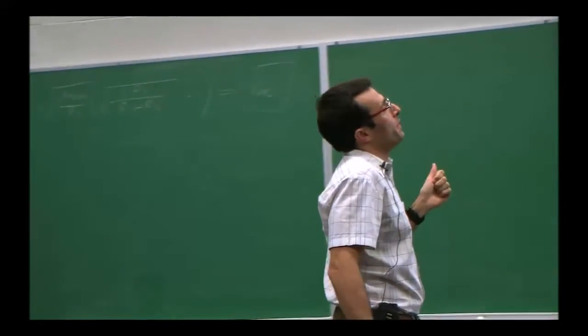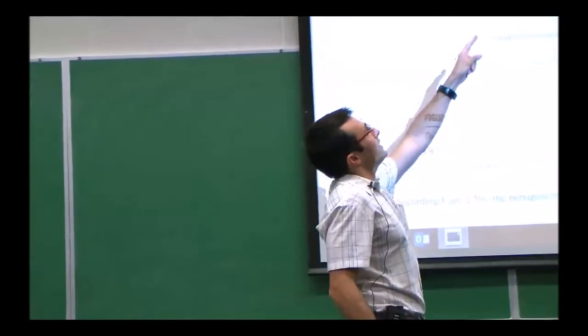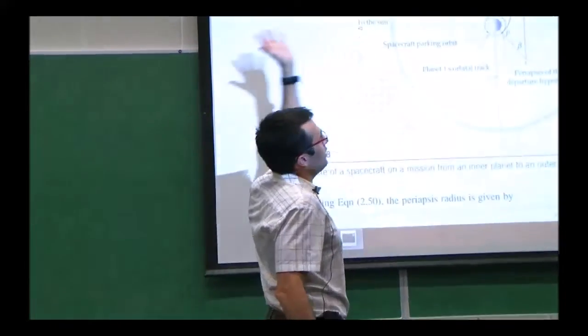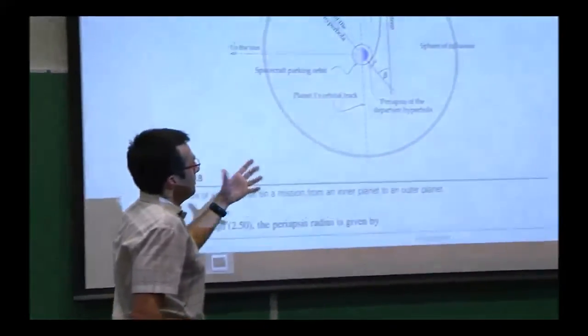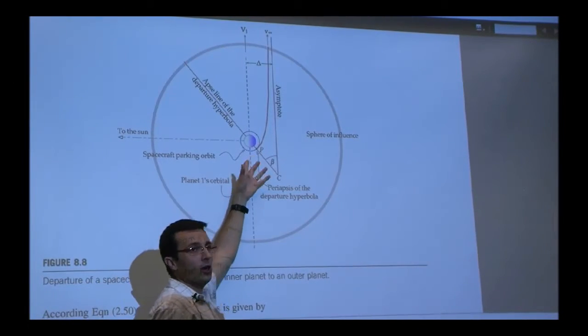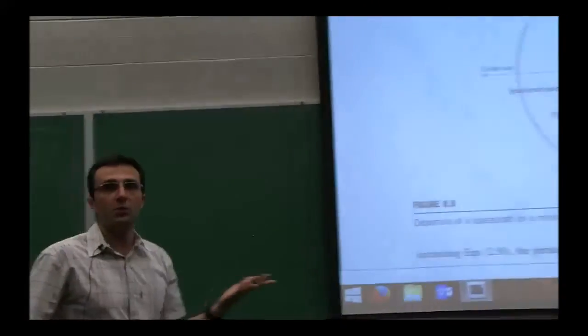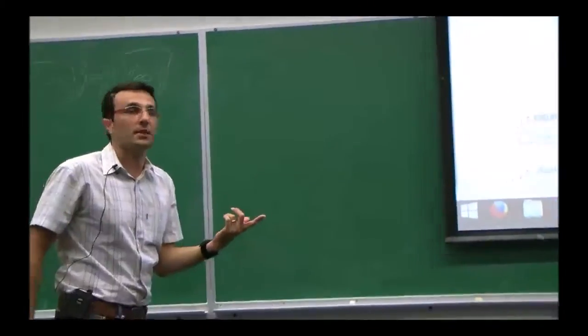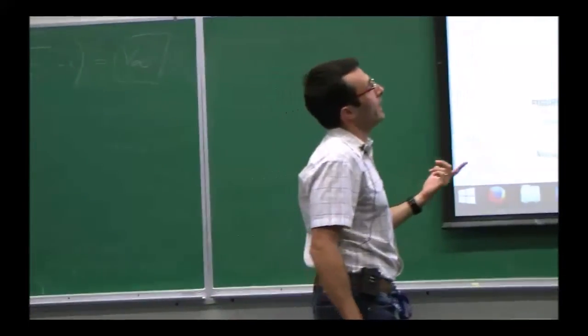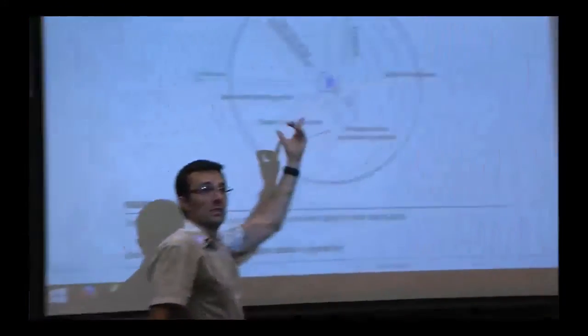But then what is really happening in practice? From the sun's perspective, you've done something that gives you a delta V, and you leave the orbit of planet 1. From the planet's perspective, though, you're probably on a circular parking orbit or something like that around the planet. You have reached some altitude, and then when you're ready, when the phi 0 is met, you actually burn an engine and go into a hyperbolic path, right?